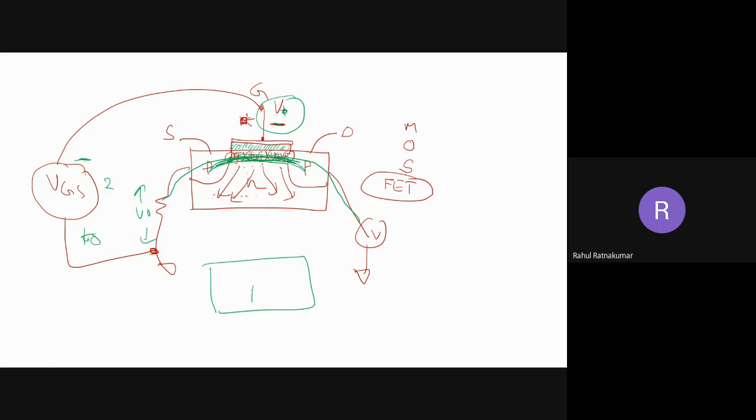So reverse is the case of the n-channel MOSFET. We have P material, we dope using n-type material, and we have an oxide, we have a metal. And now, if we apply a plus voltage VGS across the gate, and this is source and this is drain, we give a positive voltage for the current flow. Now what happens, because of the positive voltage, all the holes at the top will be repelled into the body of the semiconductor and the electrons.